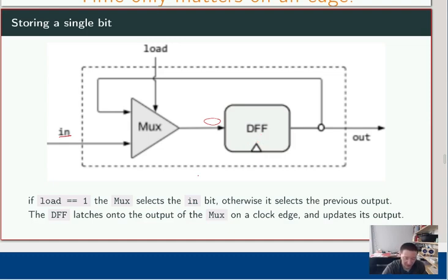So there actually is another connection called a clock that's connected to everything else in our system. It's just that in this class we don't draw those out explicitly. Just know that's what that means. This triangle means it is rising edge, and that's going to be connected to a clock signal. So we have a D flip-flop. It has an input, it has a clock. So on a clock edge, whatever input is here will be placed on the output,